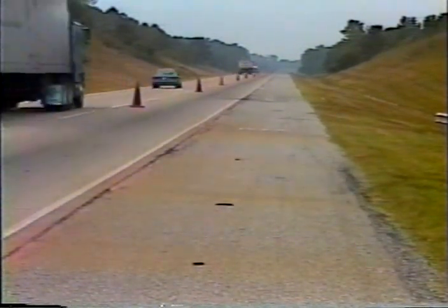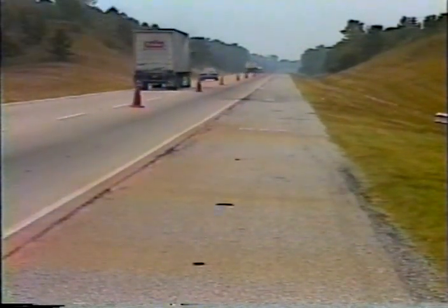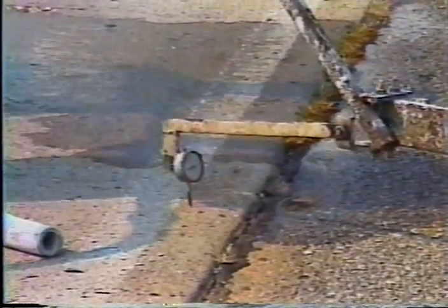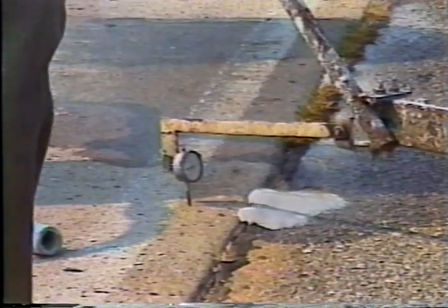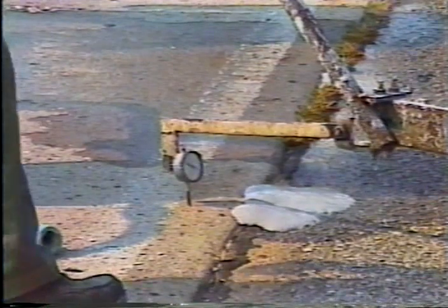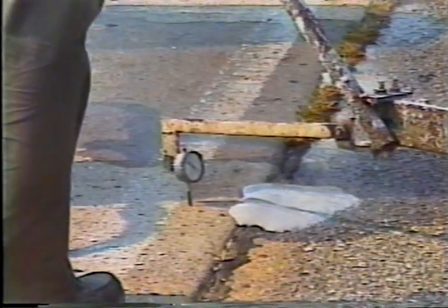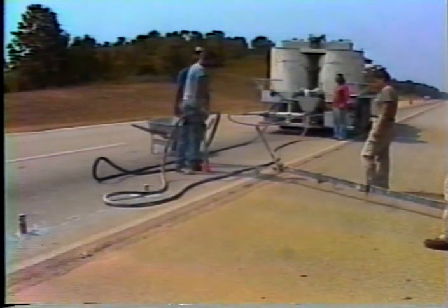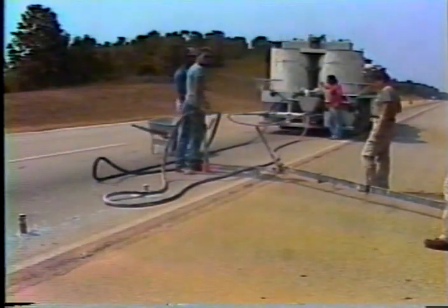Substantial loss of support has to be corrected by stabilizing the slab. Major faulting along joints can also be caused by loss of support. Here again, slab stabilization can be used, but only after making a sub-drainage evaluation and improving drainage if required. These two repair methods, when called for, should precede all other repair operations.